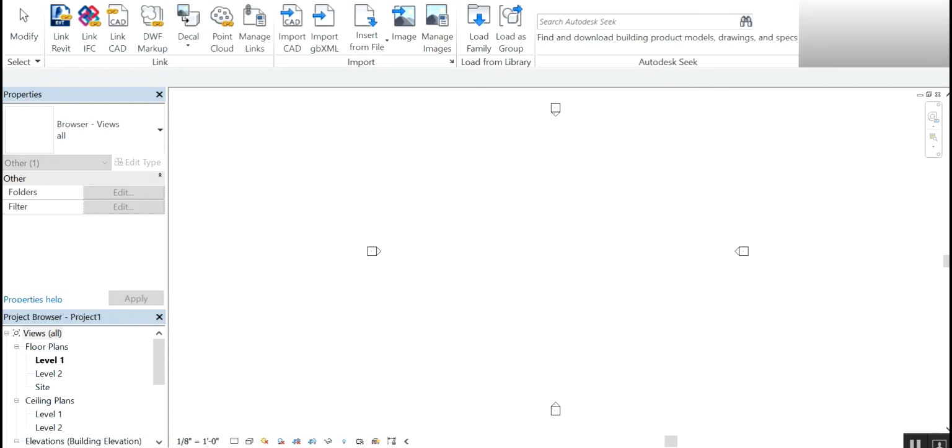Someone in your design firm will create an AutoCAD floor plan, and at that point it will be decided to make this into a Revit model. You would use Insert to insert your AutoCAD floor plan right here onto our ground plane, and it just comes in as a flat drawing on the ground, and you would simply pull the components up, extrude up walls, and then start adding in floors and ceilings and windows and doors.